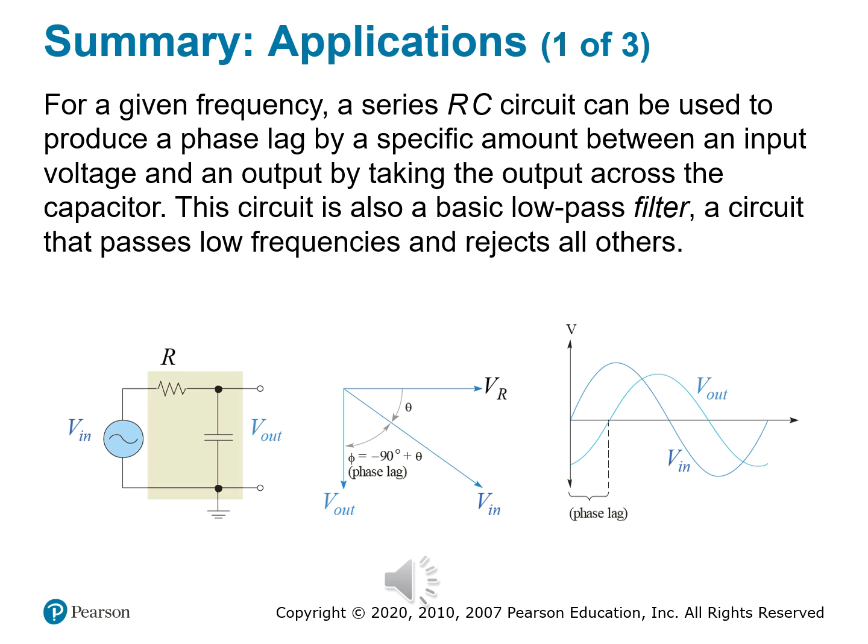So if you sweep the frequency higher and higher, you'll notice something else. Only the lower frequencies make it out across the capacitor. And so it's a low pass filter. Low frequencies mean high capacitive reactance, so most of the signal drops across the capacitor. At high frequencies, you have low capacitive reactance, and the capacitor gets bypassed, so the output voltage shrinks fast.